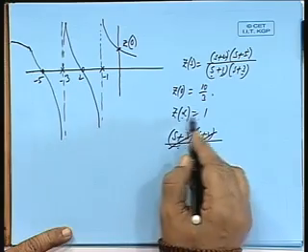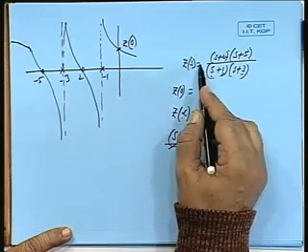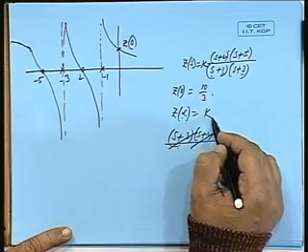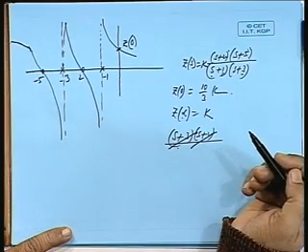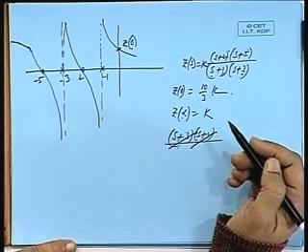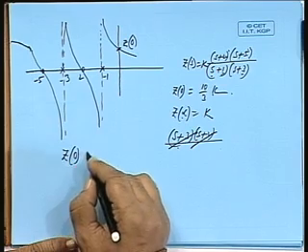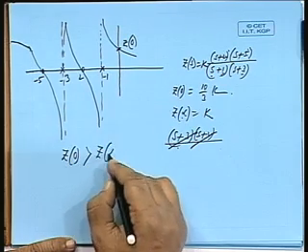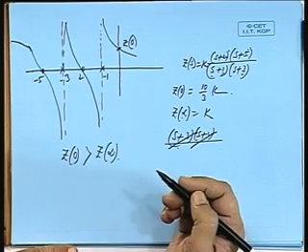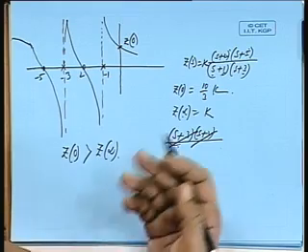So this rule does not have exceptions? No, for an RC network it cannot be otherwise. So, z infinity is 1 in this particular case, otherwise if you have a k, both of them will be multiplied by k. Okay. So, this is an important conclusion, z naught is always greater than z infinity in case of an RC network. For ys it will be just the other way around.